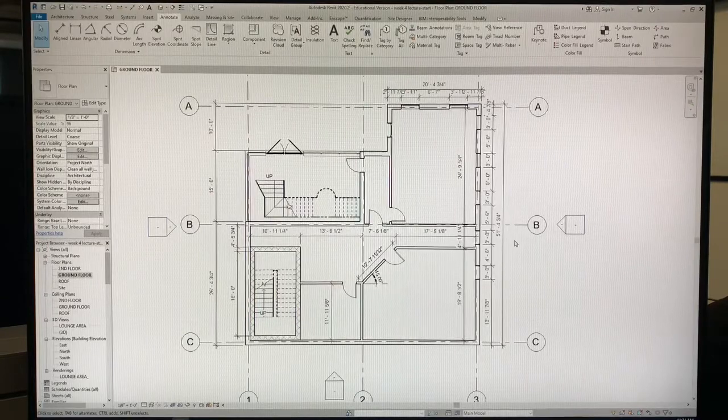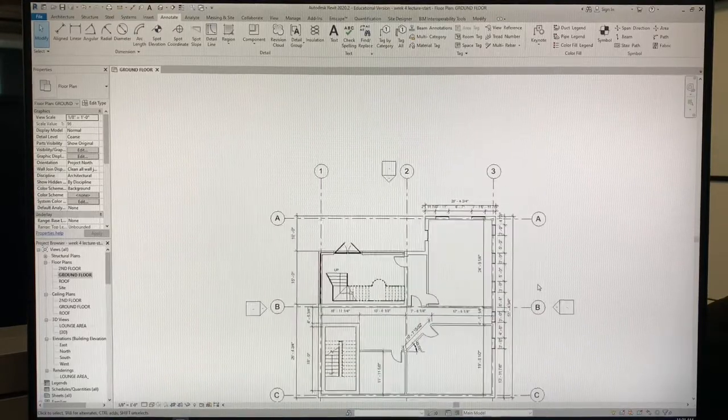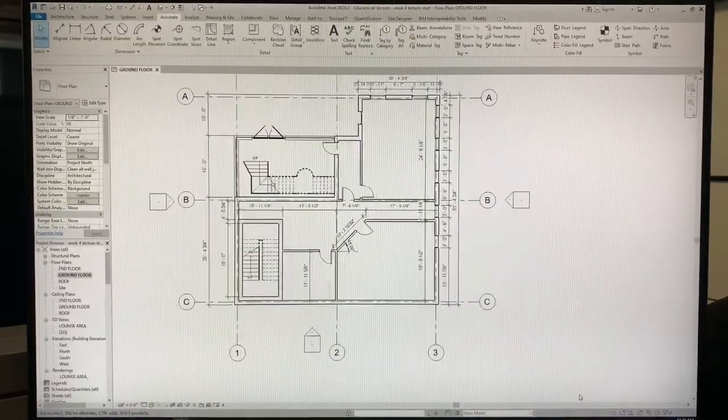But now, once you've gone ahead and dimensioned it, you're now going to see, oh, I should have put that dimension over more. Oh, I should have put that dimension over here. I should have changed that, and so on and so on. So it's always a good idea to set your annotation scale first. Okay, now, the big question is, how do I know what my annotation scale should be? How do I know? Any ideas? How do I know what my annotation scale should be?